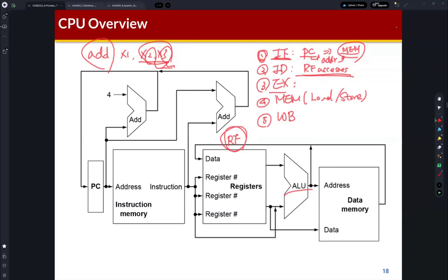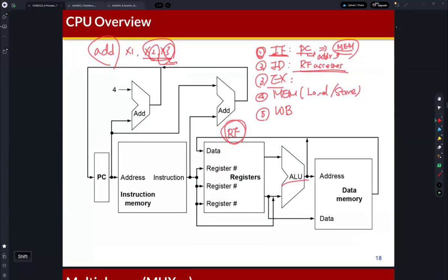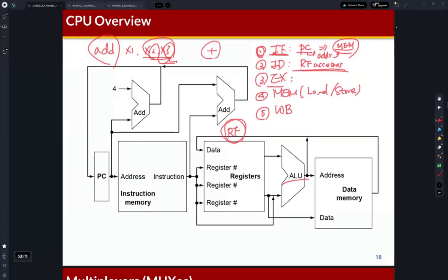So we can use the ALU, but in order to execute these operations, we also need to provide the operands. To perform add, we need the 2 operands, right? We get the 2 operands from the register file, and these operands are given to the ALU.